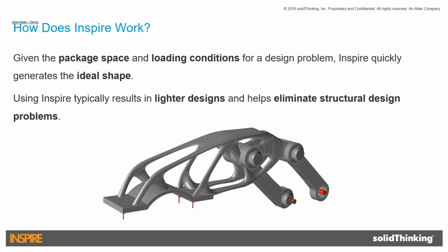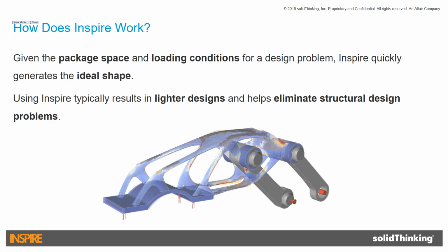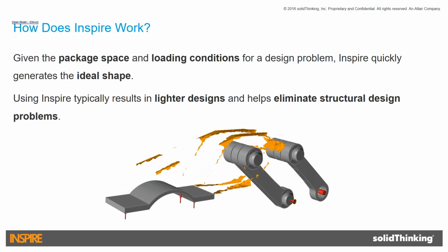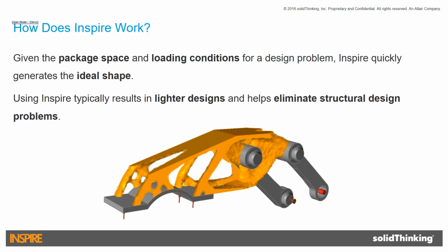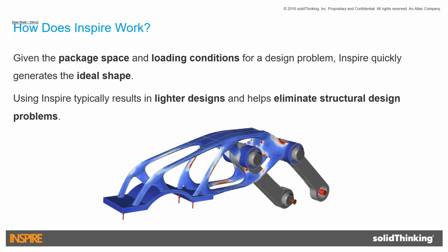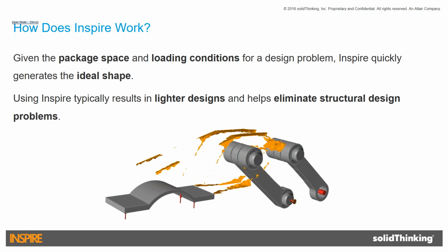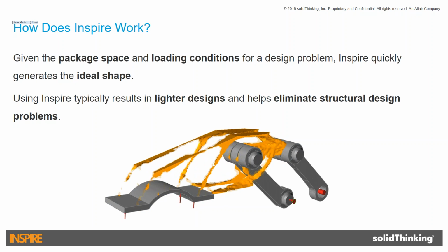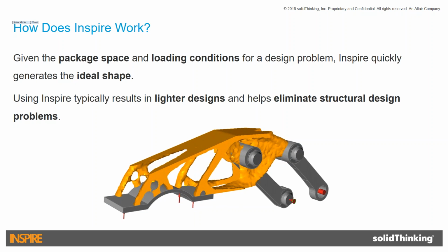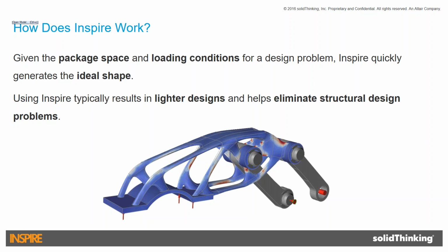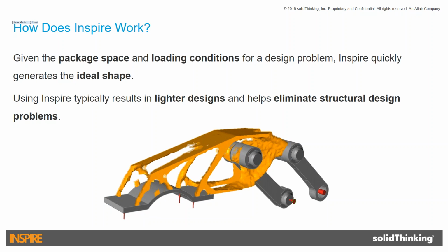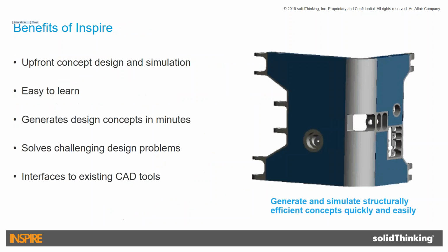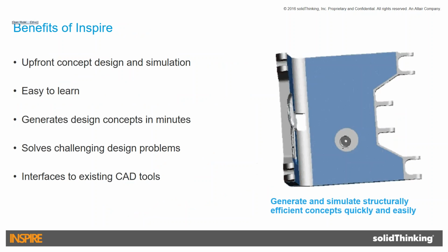As I mentioned, it results in lighter designs, but I've also seen it drastically reduce the design cycle because you can cut down on those iterations you go through between detailed design and validation. So instead of going back and forth between your simulations and your detailed design, or your physical prototypes and your detailed design, you can validate it once because you started the process using analysis and simulation as the primary driver. So it's an upfront concept design tool.